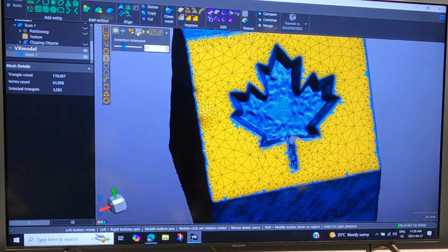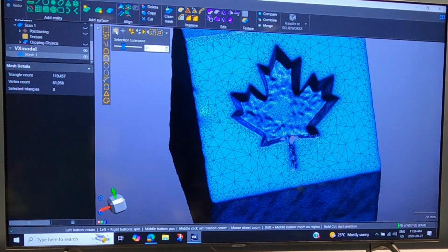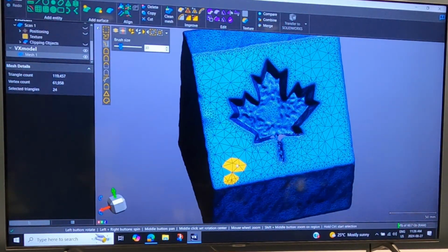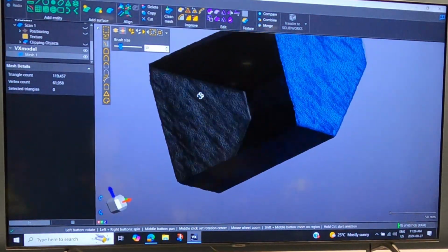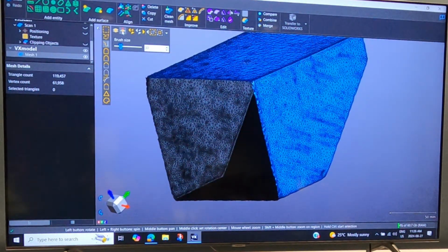Here, so that's that guy. The one modifier I didn't talk about was select back face. If I go here with the brush and do this, it'll let me select that, but if I go underneath, I can't select the gray underneath unless I choose this modifier over here.